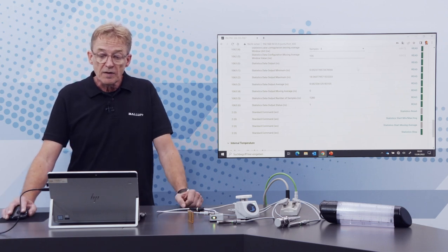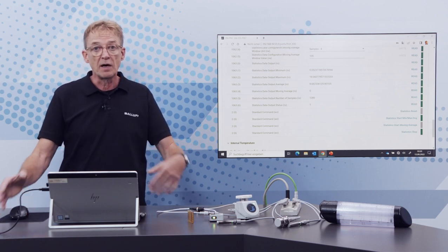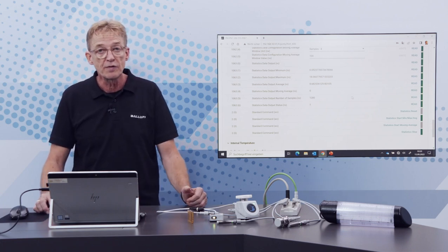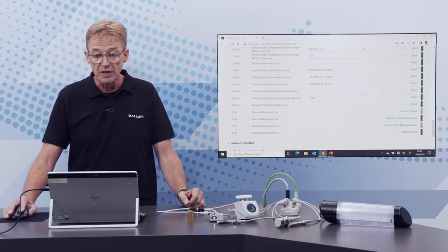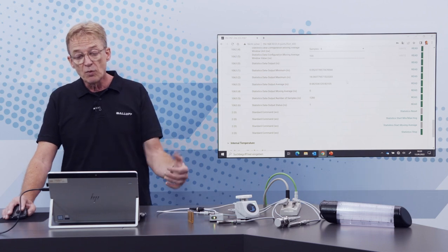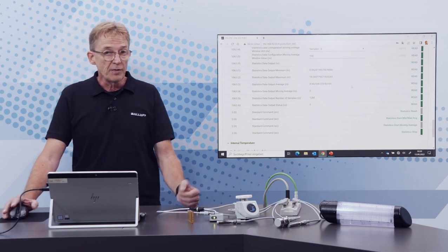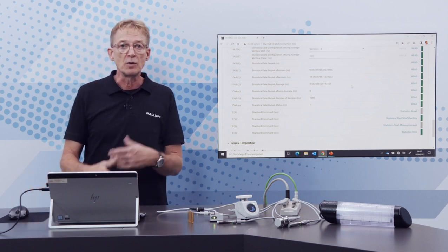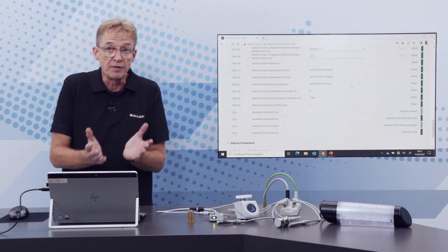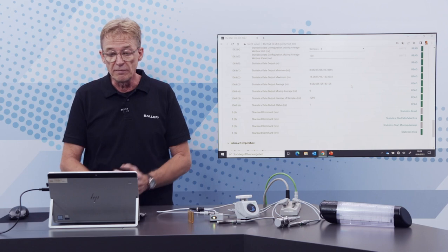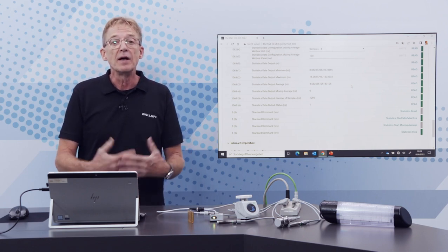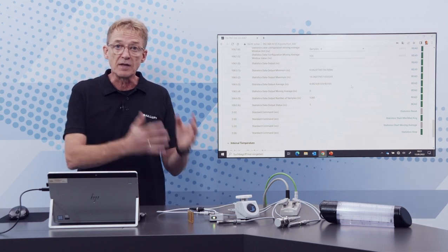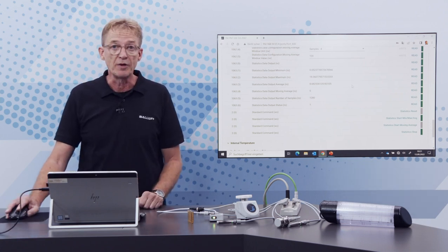So all this information here, of course, is available in the PLC or in the higher level control system via acyclic information. And that means if you need information about these basic statistics, what was the maximum value, what was the average value of a specific information, not only vibration in this case, then you have the chance to do this with the basic statistics directly in the component.